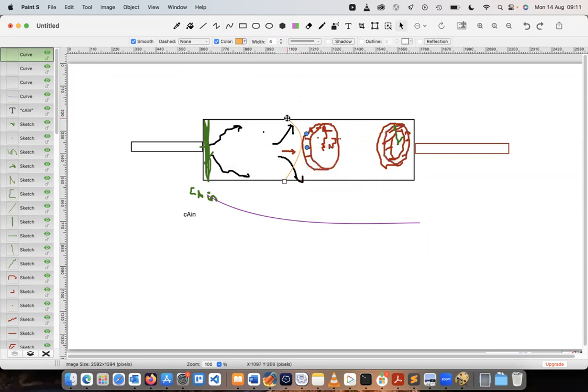So if we imagine the concentration as it's varying across the pipeline in the radial direction, the concentration is varying radially. And we know we have a lower concentration near the wall because A is being deposited on the wall. Still, the same thing is happening on all sides. If we take a vertical slice through this pipeline, then we'll see a low concentration at the top edge and a low concentration at the bottom edge. And near the center, A is not being depleted, so it will have a higher concentration.